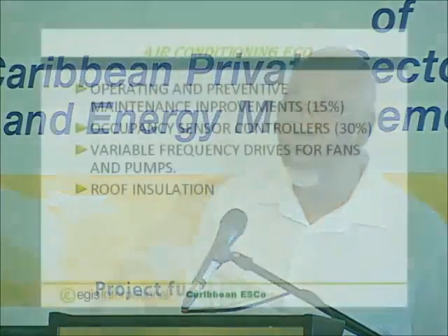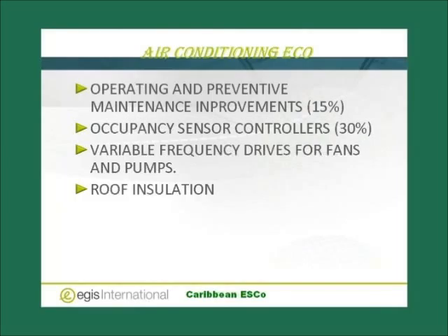Roof insulation. Now, roof insulation is not being applied effectively in our environment. Most of our buildings have 3 floors or 2 floors with air conditioning blaring. Believe you me, insulating the roof can effectively reduce your operating cost. It can effectively reduce the purchase price of a new replacement unit, maybe a more high efficiency unit, right? And what I noticed is that we have locally